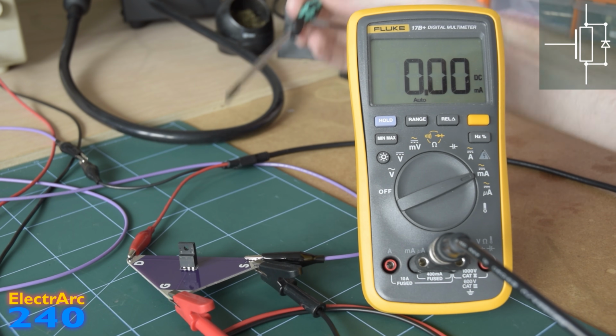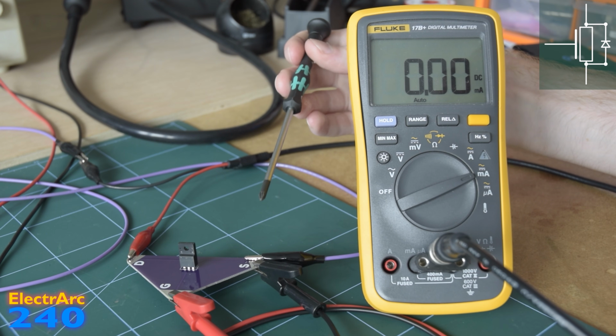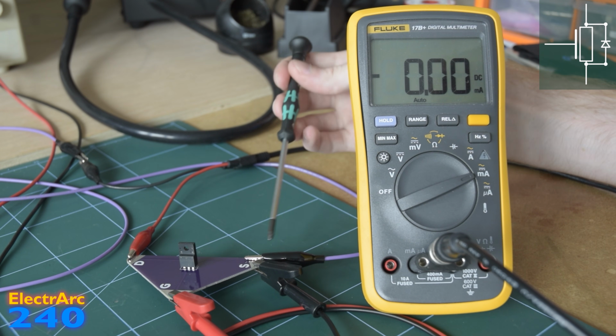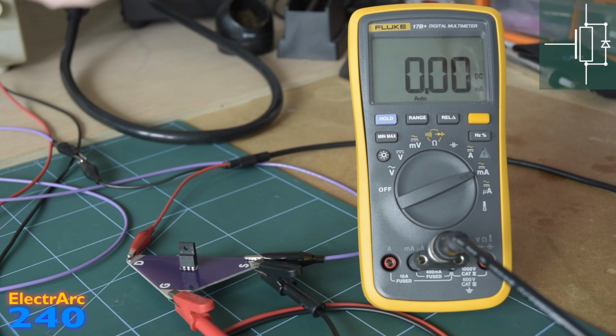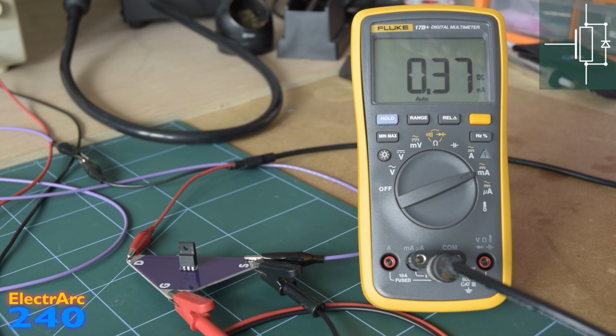What I've got here is one power supply connected between the gate and the source for our driving voltage, and another power supply connected between the drain and the source. And on that second power supply, we're measuring the current. So I'm going to start by applying 3 volts to the gate, and then I'm going to turn up the voltage across the drain and the source. You can see here we have a small amount of drain current flowing. We're currently in the ohmic region, which is where we want to be.